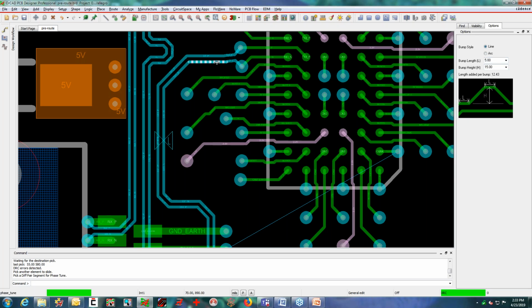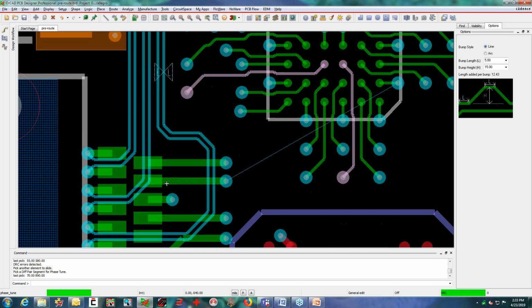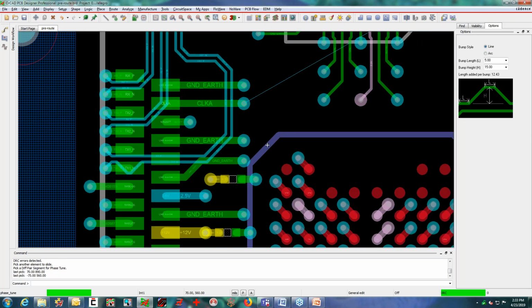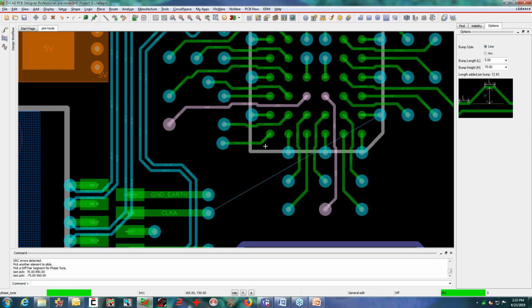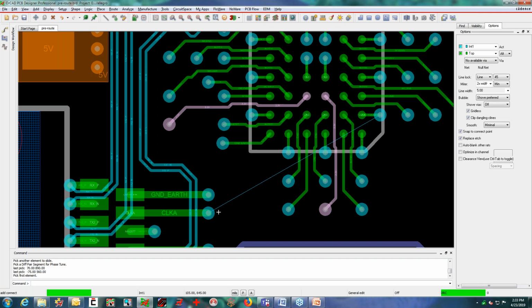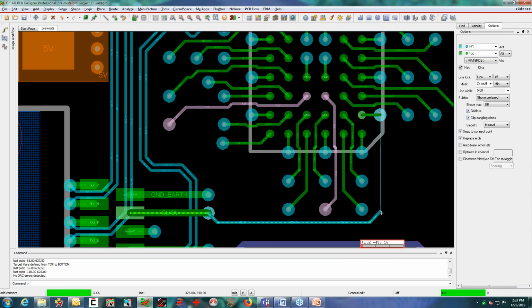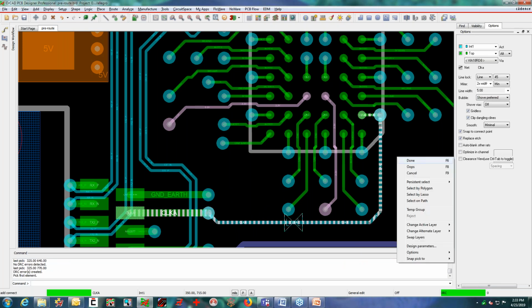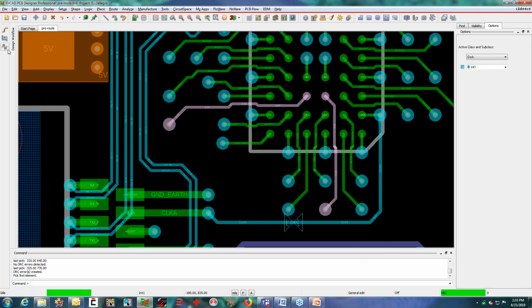And then you can strategically place where you'd want these. So I'm just going to add a couple bumps here. And now you can see that phase is now matched so that those are correct now. So if I go in and I route my clock, just going to route my clock net in here. And of course, there's some delay on this one as well. So I'm going to add some delay here.